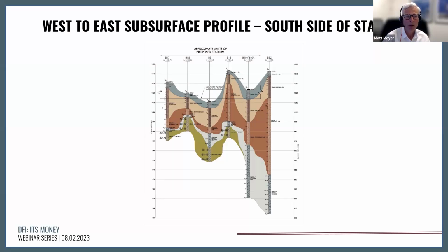Now proceeding below the maroon strata, you've got that sky blue stratum. The sky blue stratum is what's called partially weathered rock. The partially weathered rock at this site, the way we characterized it, was any material having an SPT N value greater than 50 blows per foot. Locally in Atlanta, that terminology is typically characterized by utilizing a minimum SPT N value of 100 blows per foot.